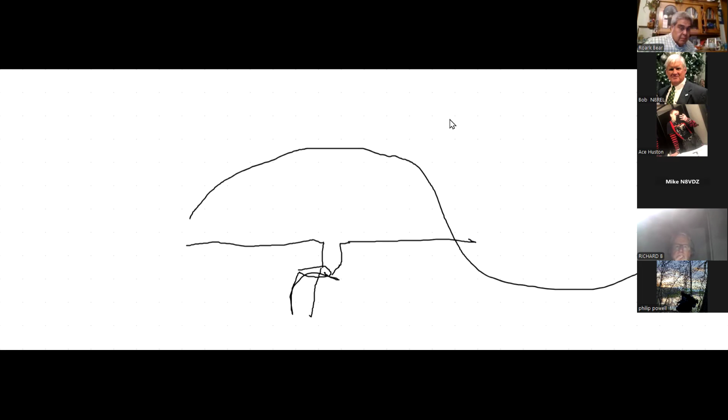It could be the coaxial cable where the center goes to one half of the dipole, and the braid on the outside goes to the other part of the dipole. So anyway, that's the dipole, and that works for just about everything.